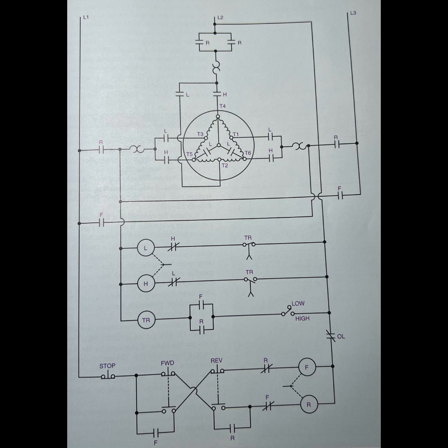This operation drops out contactor L and the normally closed interlock L energizes contactor H. The motor is now at high speed.